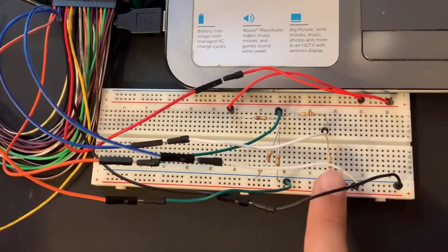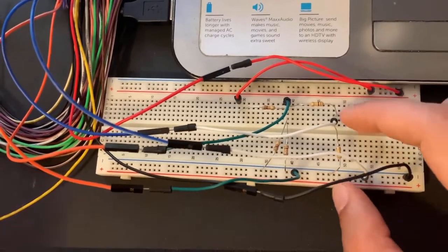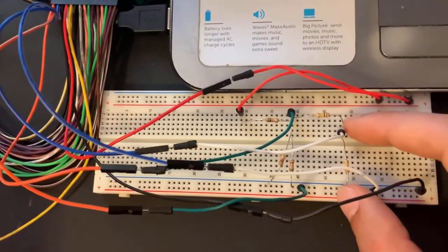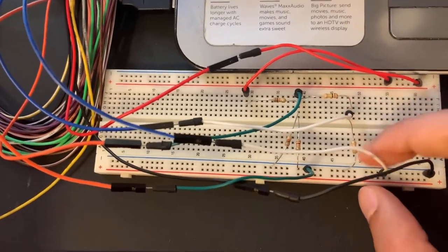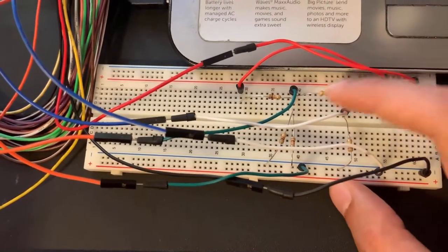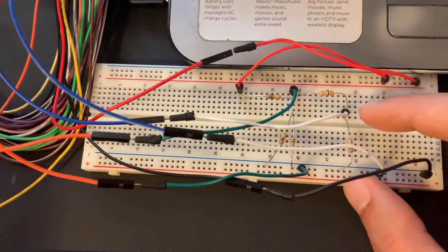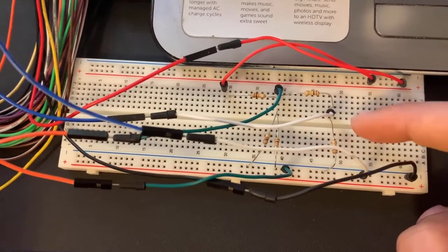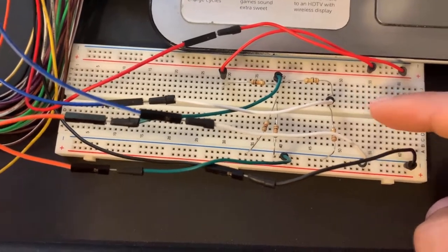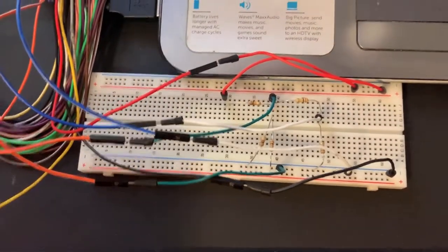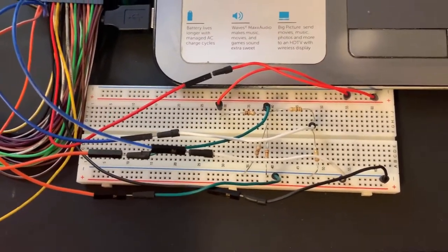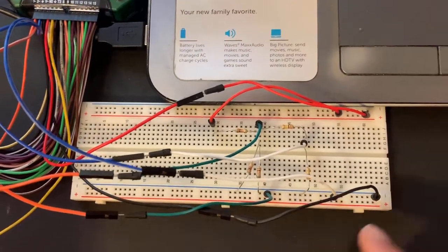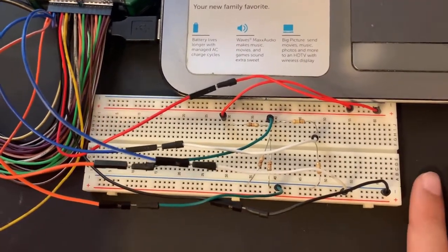And finally, for the final resistance, the voltage over the resistance is equal to V2, and the current flowing here is also I3. So if you multiply V2 times I3, you get 0.365 microwatts. The numbers you get can be a little bit different, as we said, due to the tolerance in the resistance, but it should be very close to these values.